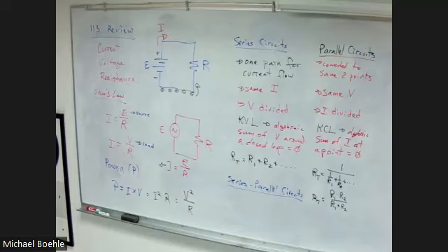And if you want to get technical, just to peek ahead, resistance is the same thing, but the phase shift caused by a resistor is zero. The phase shift caused by a capacitor and an inductor, I already gave you a hint earlier, 90 degrees. And impedance could be somewhere in the middle. Basic idea.